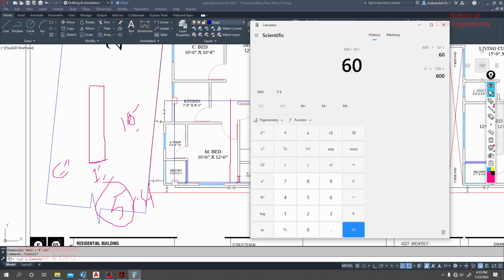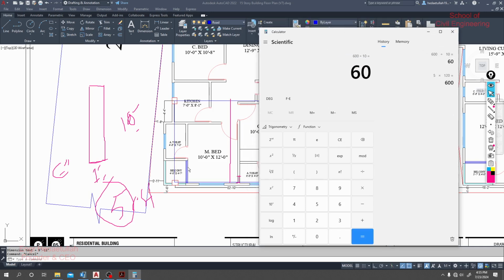That means if we take a wall with 6 inch thickness, its weight per square feet will be 60 psf. Clear? 60 pounds per feet. Then if you multiply your wall height with that value, you will get your total value.